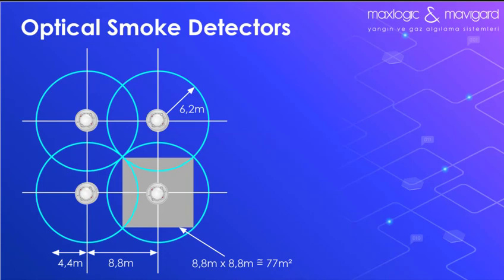If the projected area has a slope ceiling, for detectors at or near the top, the horizontal distance given above may be increased by 1% for each degree of slope, up to a maximum of 25%.